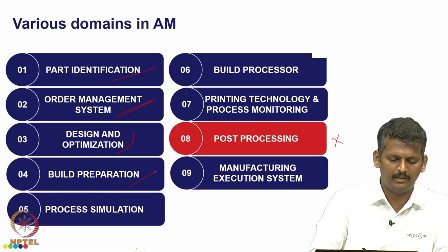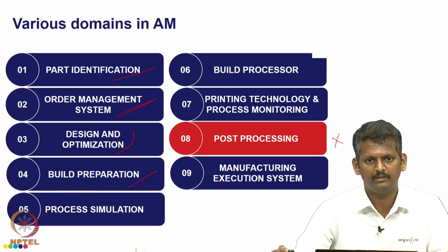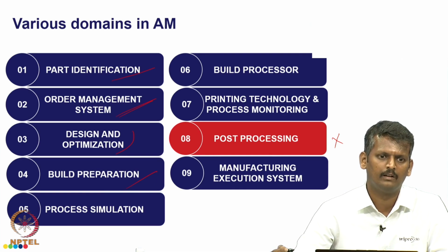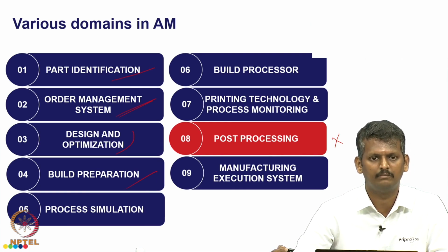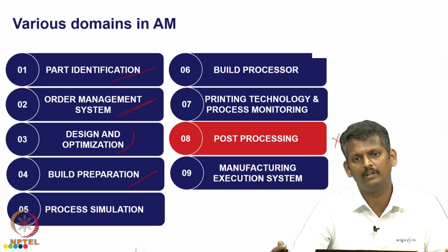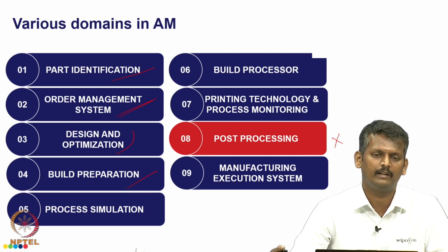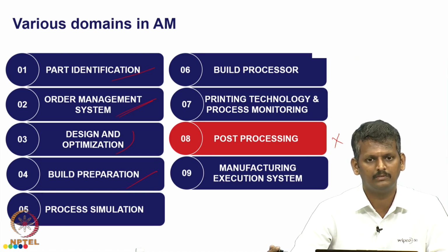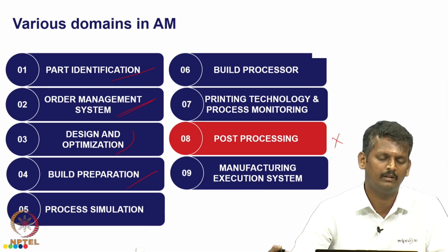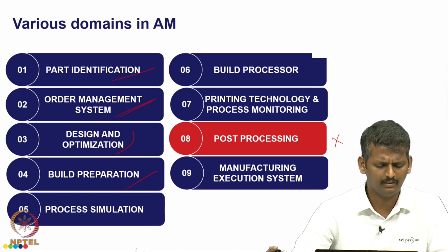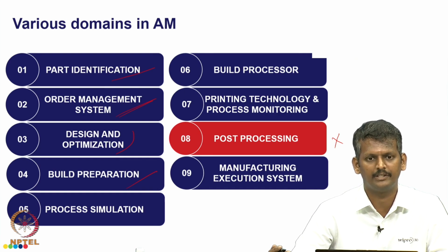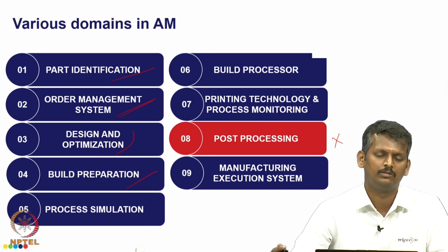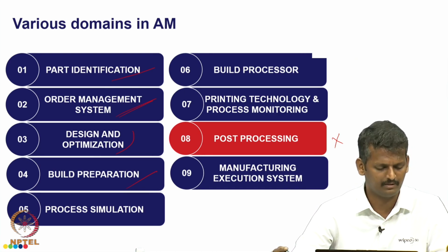And now coming to build preparation. When it comes to build preparation, we have work like fixing and editing the mesh files, because whenever we make a design, we basically convert it into an STL file format, and that STL file need not be perfect all the time. So there will be an operation of fixing and editing the STL files based upon our requirements, and the other things are support structure creation and orientation setting. These kinds of things come under build preparation.